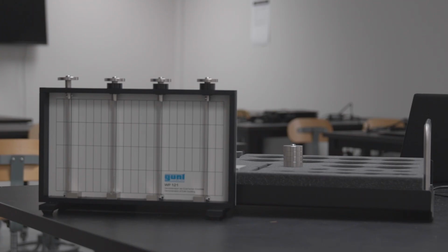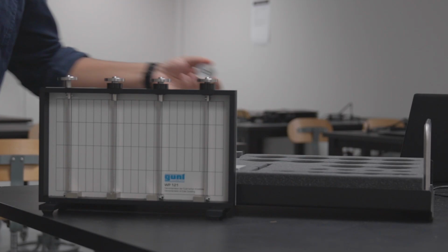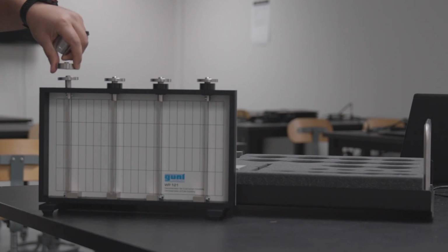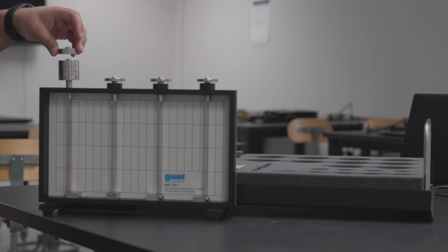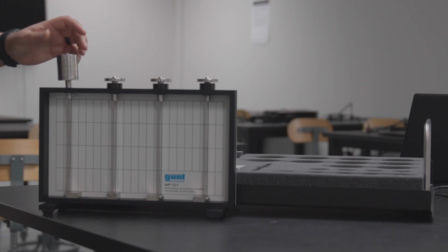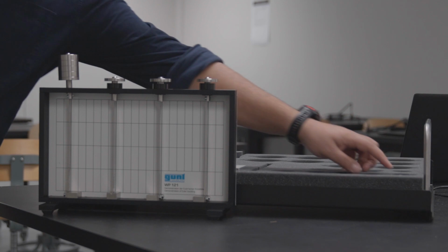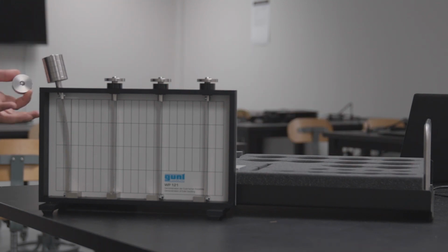Okay, so the eventual goal would be to add load again to each of the columns one by one. Essentially, let me do the first one. Add 1 Newton, no buckling. 2 Newtons, no buckling. We see it is starting to buckle, but it hasn't buckled yet. 3 Newtons, no buckling. 4 Newtons, no buckling. I'm not sure, it should have buckled by now. Well, yes, it did buckle, okay. So it did buckle at 4 Newtons.